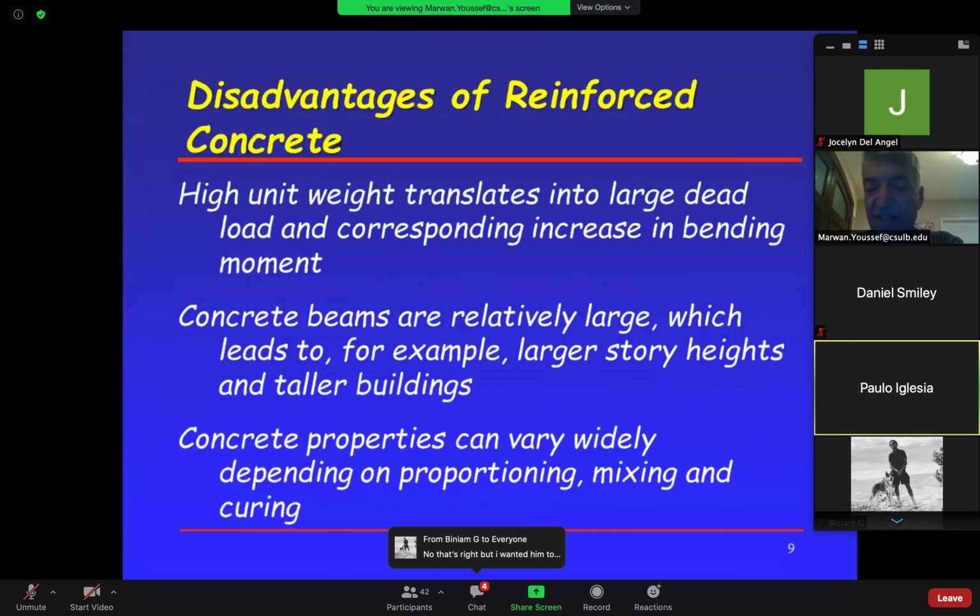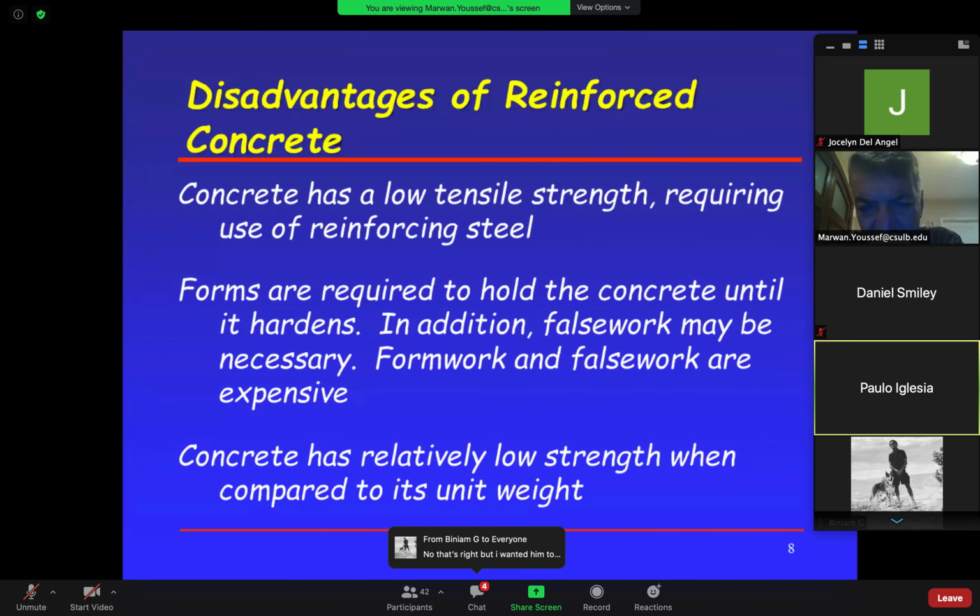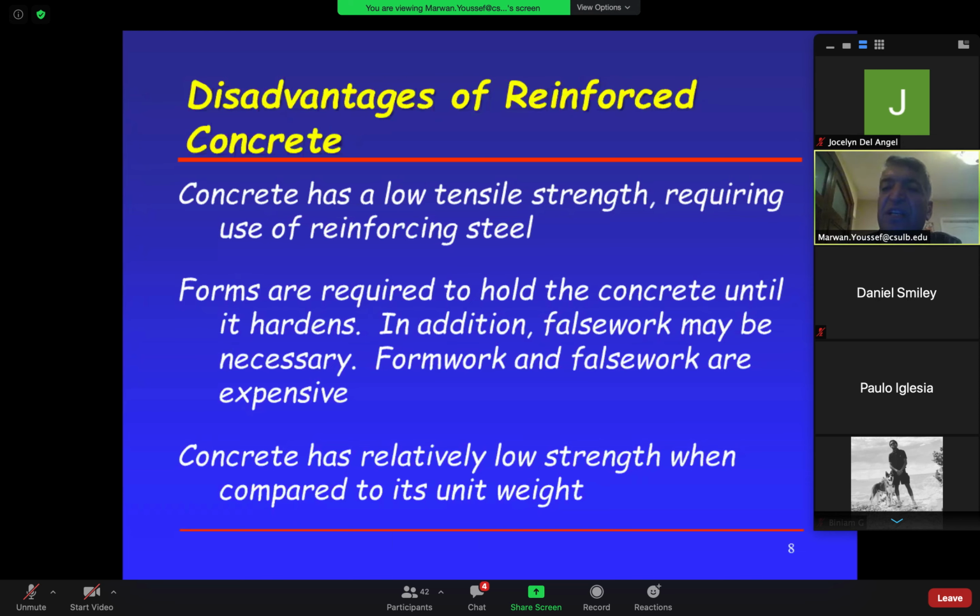I have a question. Yes. Is the weight of the beam considered dead load? Yes, very good question. The weight of the beam is considered dead load, but that's not the only dead load you will have in the structure. So we will add it to the dead load. What other dead loads could the building have? Think about this. You have a room in a hotel. That room is supported by beams below it, so the weight of those beams is dead load. But what other dead loads do we have? The weight of the slab that you're standing on is a dead load. The weight of the tiles you put on the slab is a dead load.